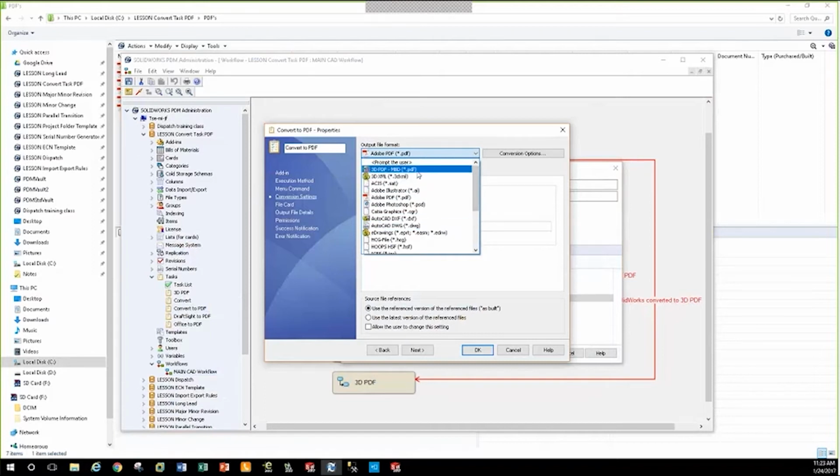As you can see in here, yes, we made PDFs. I can make 3D PDFs. I can make 3D XMLs. Obviously, I can move down into DXF if, say, you want to send a stamping. A good example is sending a flat pattern of a stamping out to the shop floor for laser or water jet or plasma. They like to have DXFs. I can make DWGs if I want. I can also make my e-drawings. If we want my default viewer out in the shop to not be Adobe, you want it to be e-drawings, well, we can make the EPRTs, ASMs, and EDRWs.